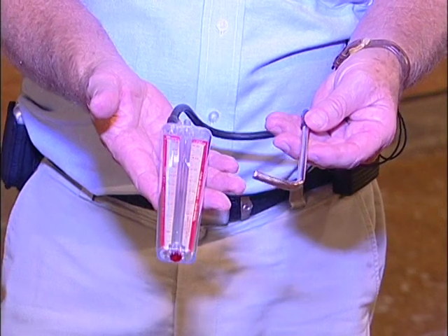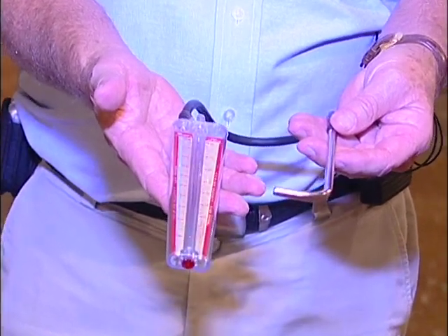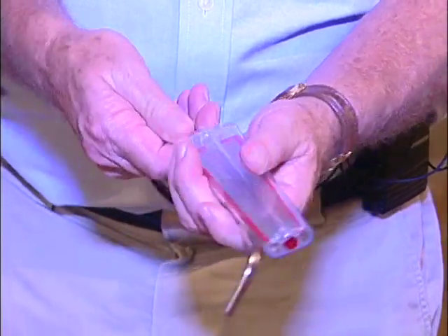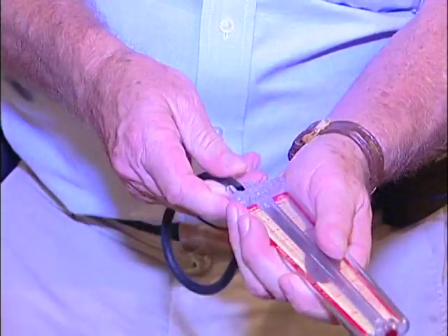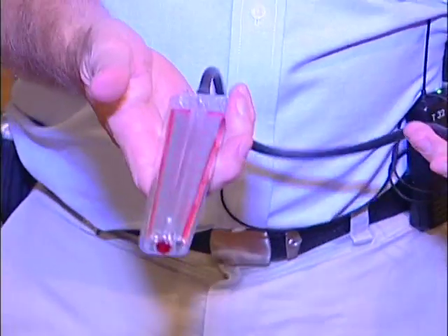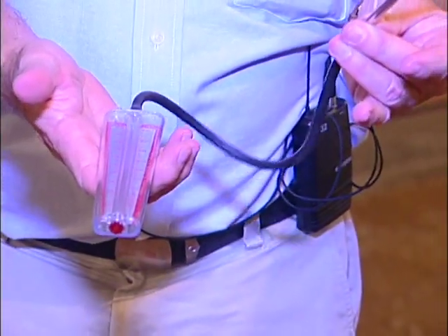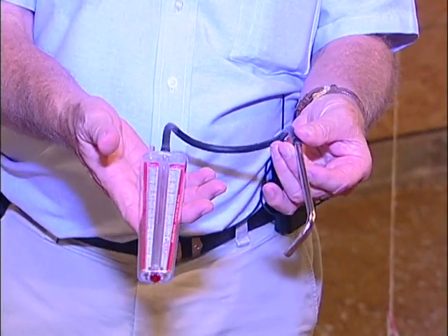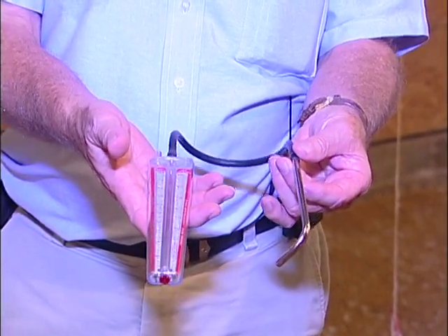Now, if we wanted to use the same instrument to measure the actual negative pressure in the house, then we just move this over to this, and if we're on the outside of the house, stick this through the door or through the inlet, and now it reads exactly what the pressure is to atmosphere.